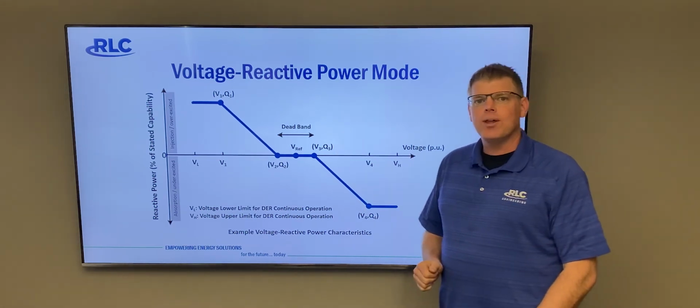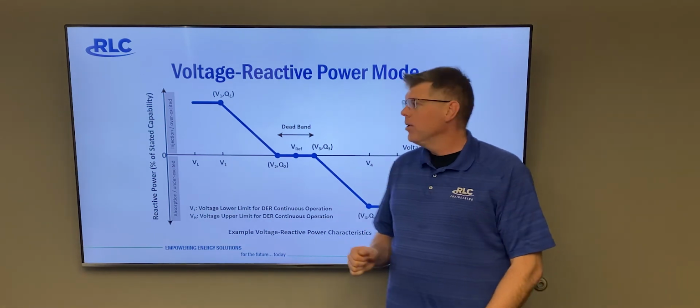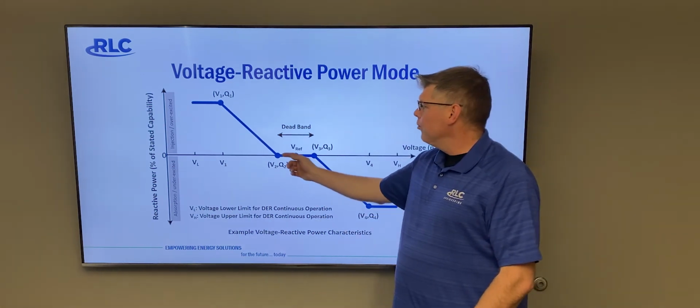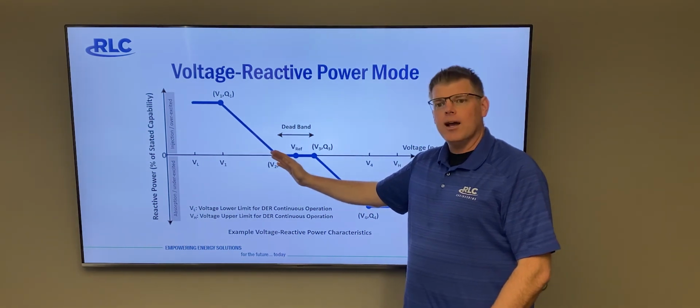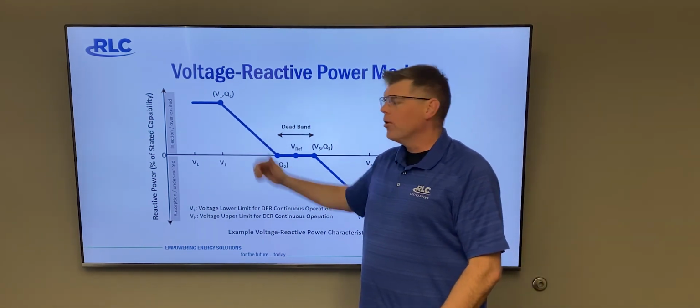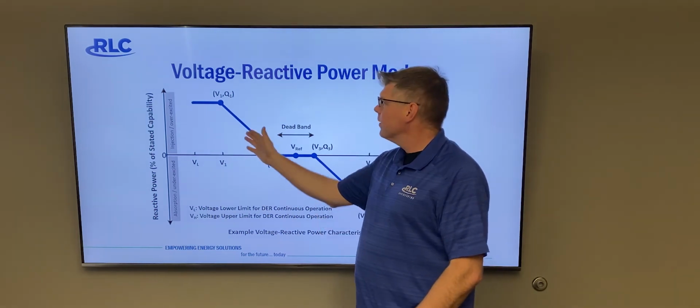This mode can actually help in low voltage conditions where there's a lot of load. If the voltage begins to drop below the deadband, the DER can actually inject reactive power, boosting the voltage up, as we see here.